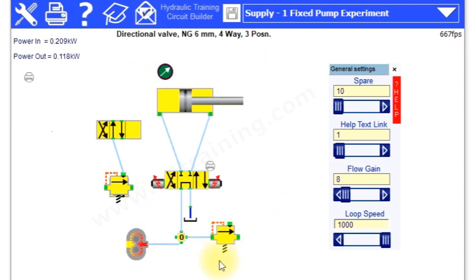Obviously, if you put your own systems in, don't put the whole circuit in. You just take a single cylinder and valve combination. That's the way we generally use the simulation program. Keep the speeds up, and this is the important part: how the valves within a unique small section of the circuit actually work. Okay, enjoy.